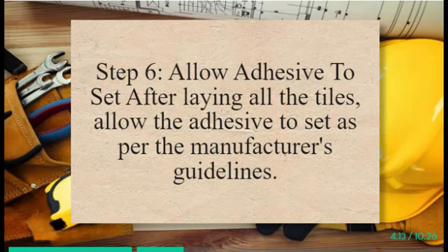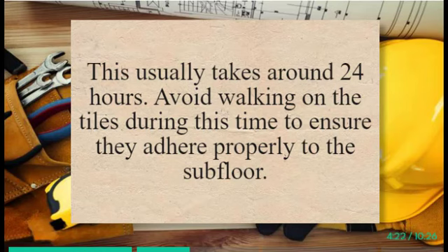Step 6. Allow adhesive to set. After laying all the tiles, allow the adhesive to set as per the manufacturer's guidelines. This usually takes around 24 hours. Avoid walking on the tiles during this time to ensure they adhere properly to the subfloor.